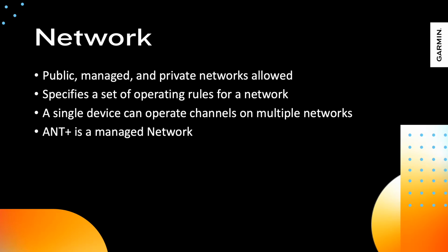A network can be used to specify a set of operating rules for all participating nodes. A managed network defines rules and specific behaviors governing its use. This allows products from different manufacturers to be interoperable. As we will see later, ANT+ is one such managed network. As a quick tip, make sure you set the correct network key for your device. For security reasons, ANT will always return a success response, even if you entered an incorrect network key.